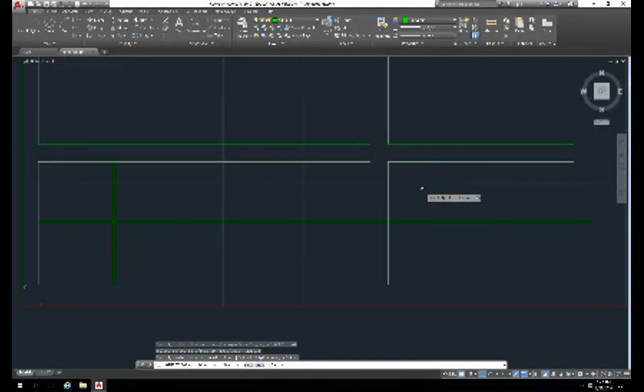And the angle is 30, but we're drawing from this. So let's see. Is the angle going to be 60? Okay, I'm going to try and see if it's still in the offset command. Okay, so line command, and this is a shortcut. At sign, length of a line, we'll just say 1, and then less than sign, or this greater than sign. And I'm going to try 60 degrees. That actually looks right. 60 degrees.